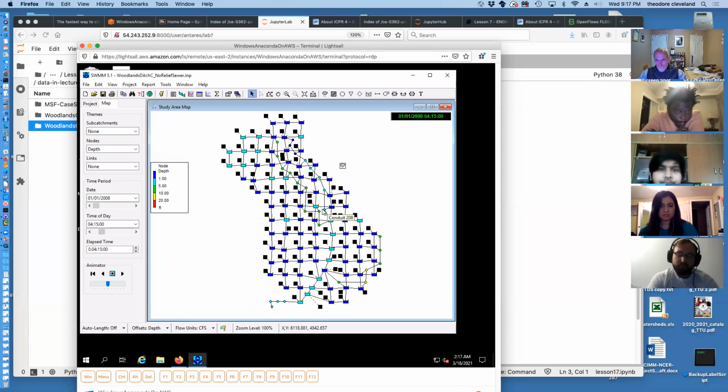And here we have this particular sewer is probably full of water. These are 2-foot diameter sewers, so if it's showing a flow depth of 5 feet, these are definitely surcharged sewers. And we have between 1 and 5 feet depth up here in the north part of the subdivision. So this light blue is now, think of it as flooded.